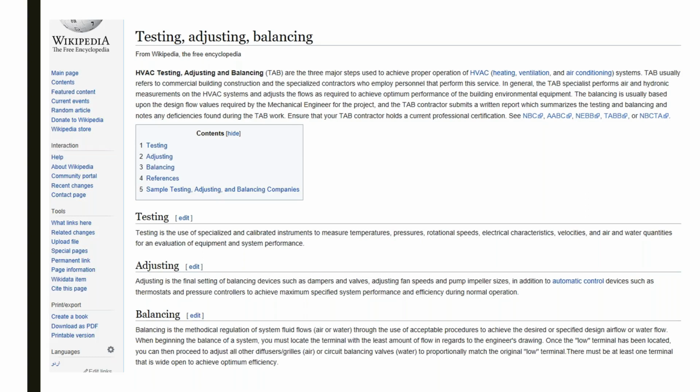These systems are designed appropriately with the right size duct, and so if I just turn this air handler on, I'm going to get the right airflow, right? Or I don't need to test and balance this VAV system as long as I can read the CFM on the box. It's got the right CFM, right? Well, no, nobody really knows, because until somebody actually tests it and says, yes, it is, or no, it wasn't, and now we fixed it, now it is, you don't know.